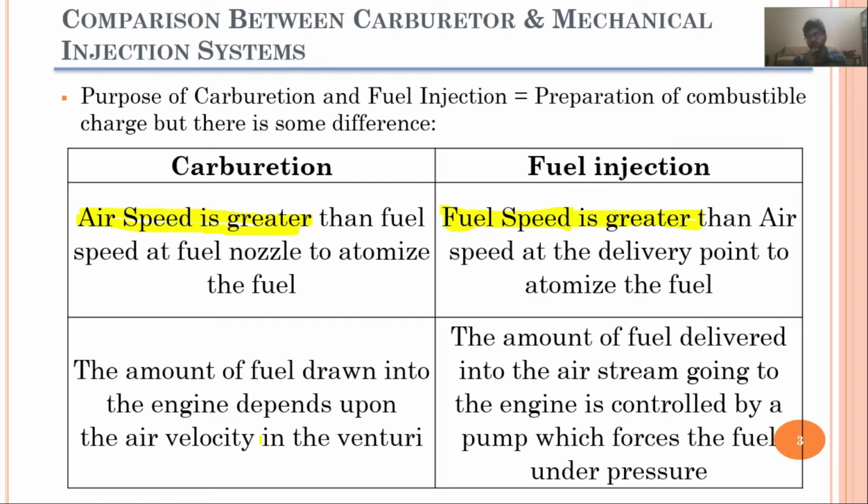Velocity will be greater when there is more pressure drop between the 2 points which I have shown in the figures in the last video tutorials, from section 1 to section 2. When the pressure difference across these points is higher, the velocity at the venturi throat would also be high, because the air is gaining speed, it is gaining kinetic energy at the expense of the pressure drop.